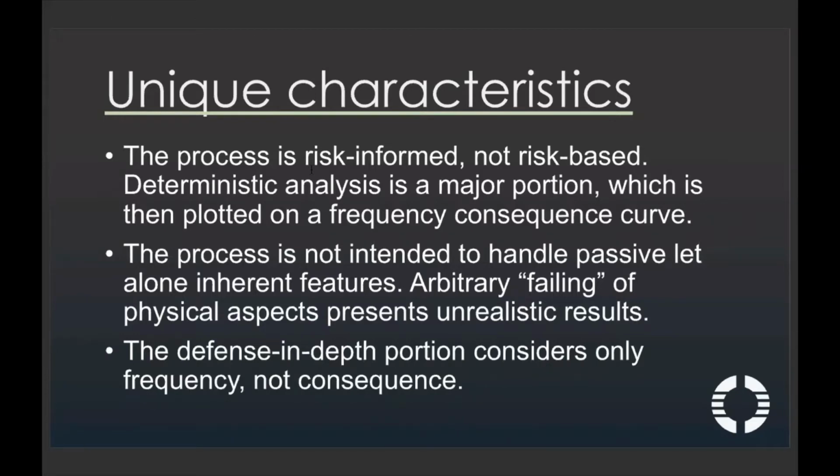Lastly, on the defense in depth portion, I mentioned earlier how it ends up deterministically failing certain things, but there are also tables that create ways of categorizing components based only on whether their failure increases the frequency of an event, not necessarily the consequence or the combined risk. Of course, everyone on this call probably knows that risk is frequency times consequence.